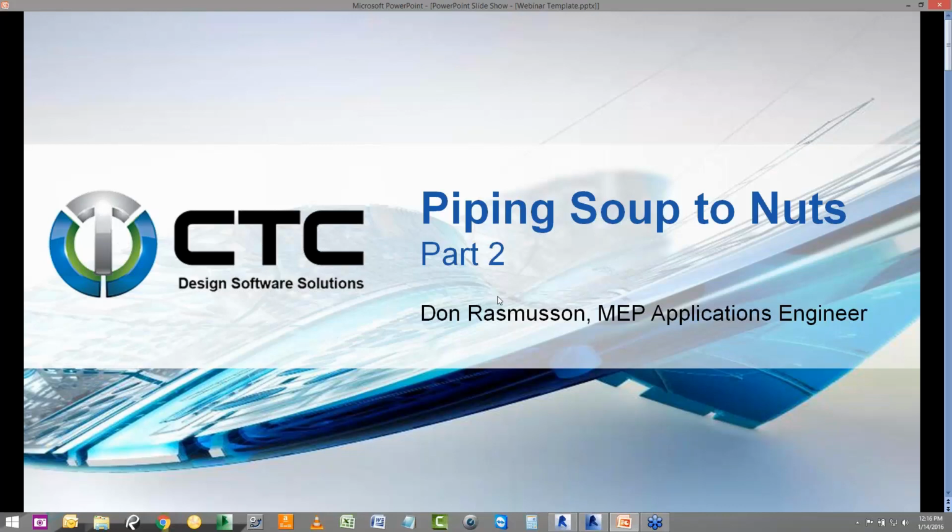And today, for Piping Soup to Nuts Part 2, I want to cover a little bit about visibility. So we're going to look at filters, and we're going to look at templates and how that can all be applied to pipe and used to quickly create views for you, just so you can see what you want to see. And then we're going to get into some fittings, and we're going to look at lookup tables and how those lookup tables drive the fittings and the relationship there.